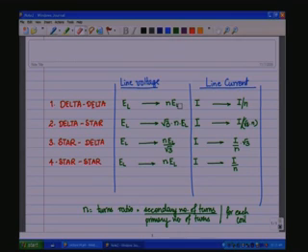Let us say you have a 400 volt system and the windings of the primary side should withstand 400 volts and the windings of the secondary side should withstand n times 400 volts, because in the delta connection the windings come directly across the terminals or the line.